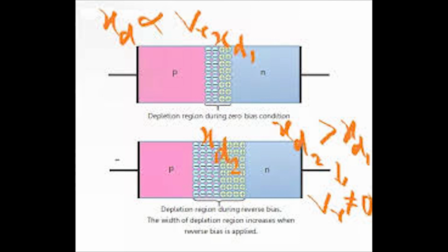However, a very small leakage current does flow through the junction, which can be measured in microamperes. One final point: if the reverse bias voltage applied to the diode is increased to a sufficiently high value, it will cause the PN junction to overheat and fail. This may cause the diode to become shorted and will result in the flow of maximum circuit current.